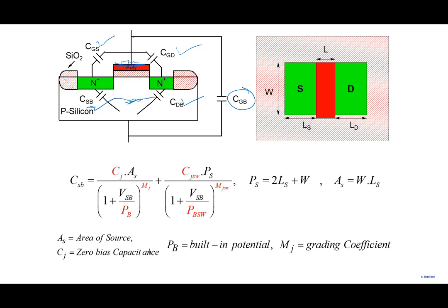As you know, once the inversion layer forms, depletion capacitance doesn't change. So if you increase the gate voltage, the depletion charge in the body doesn't change, to first order. So there is no communication between the gate and the body. You change the gate voltage, nothing changes in the body. Once you are under strong inversion, nothing changes in the body.